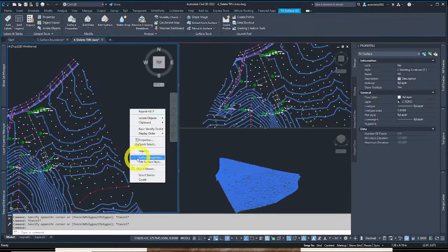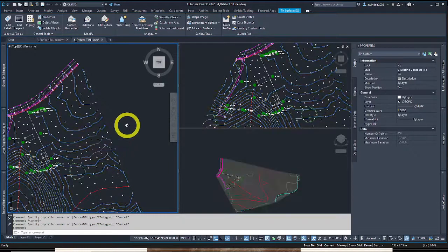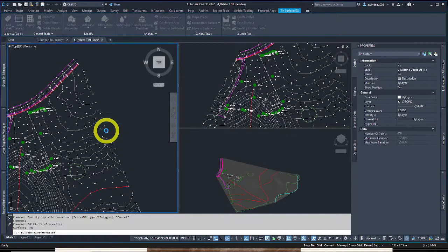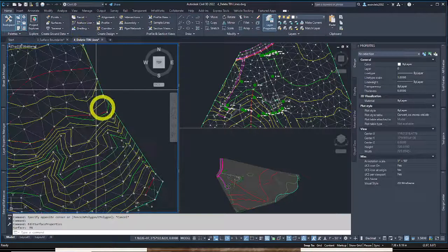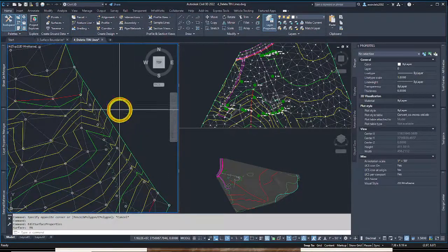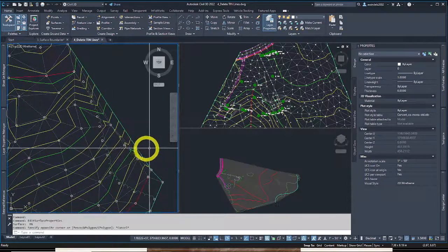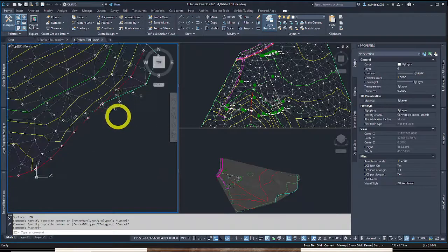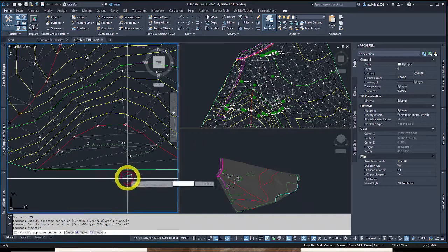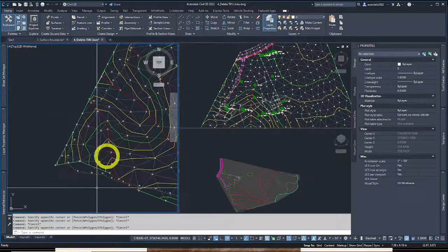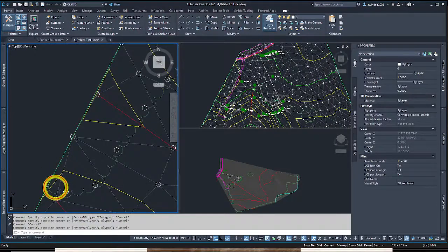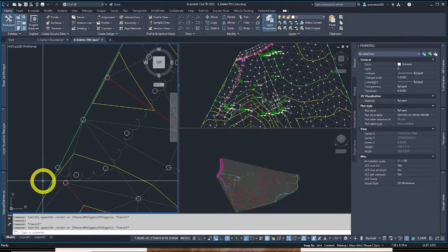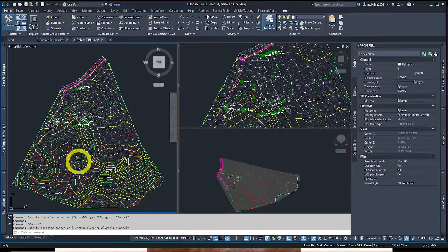So if I change the surface style properties to something where I can see the TIN better, let's change it to contours and triangles. This one's pretty well done, but right here, I'll delete out all these triangles. They're triangulated in a funny way that's not realistic. You get an eye for triangles as you go on, especially with existing undulating surfaces. This one looks okay. It's a flattish area. This one would be a little nitpicky, but I would delete this area of the surface out right here. Okay, that's some of the main triangles we're deleting out.